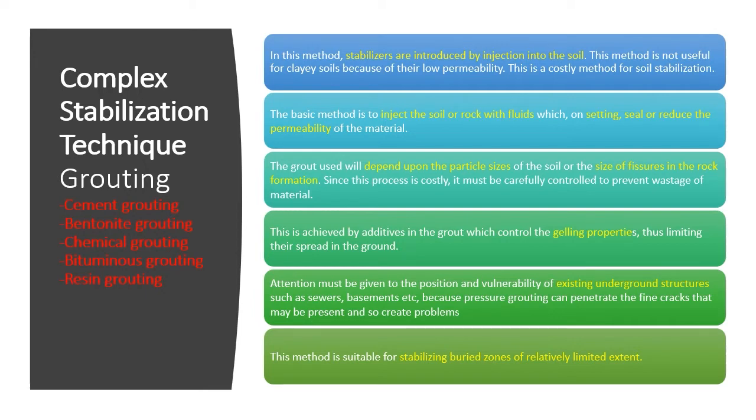PFA is generally used as a ground modification and stabilization material, whereas the expensive chemical mixes, such as resin or epoxy mix or others containing microsilica, are used to fill small voids and improve the groundwater resistance. Cement grouts can permeate silty fine sands, while chemical grouts can permeate even finer grained soils but become increasingly expensive as higher permeation is required.